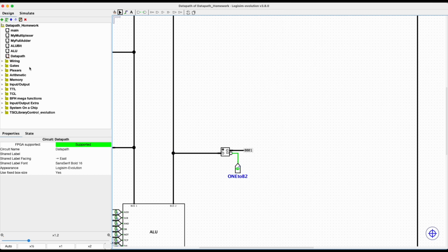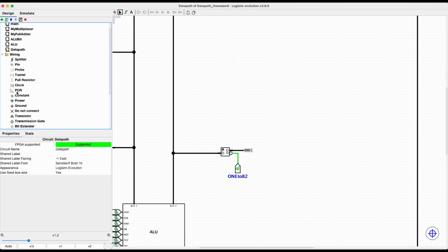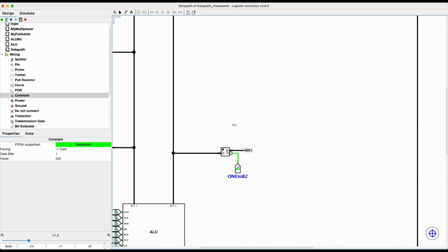And so how did I do that? Well, I grabbed the constant and made it 16 data bits wide and turned it upside down. And now you can connect that. This here is just a tri-state buffer. And this again, I enable switch, and then I just took this guy right there. And if you notice, that's all zeros, so we can just say 0, 0, 0, 1. So that's just the number 1 that we can hook in there.